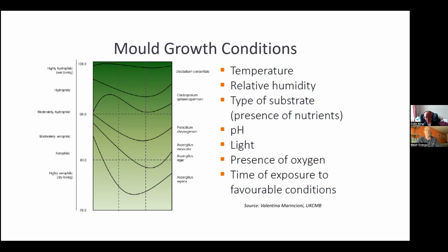and it can give you a real-time warning. And it can measure things like internal moisture load by measuring active water. It also does relative humidity because that's relatively simple, and you can see whether it's a transient moisture load or whether it's a permanent one, which active water would be. And then it can look at temperature. You can see whether the people are playing their part in being able to heat the property up to a reasonable level. You can use CO2 as a proxy for occupancy. We know how much CO2 people give off. So if there's a high CO2 load, it may give an indication of over occupancy, therefore over moisture load. But yeah, I can dig a few out and send you the links if you want.